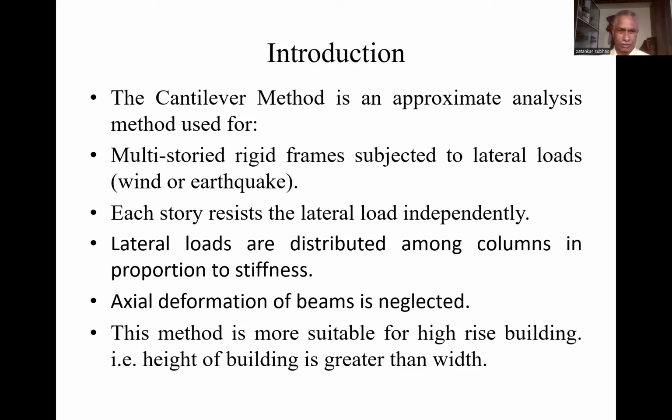The three methods used for the horizontal load, that is called the lateral load, are the portal frame method, the cantilever method, and the factor method. For the vertical load, we use the substitute frame method. Only one method is there.